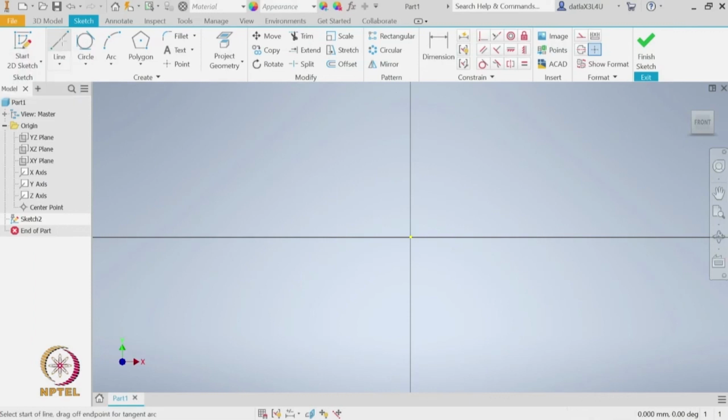So, I can start with a straight line, saying that this is one straight line, 2, 3 and 4 points. I will press the escape button to say I am done with creating these multi segmented lines. Now let us use this extend button. Once I click extend and come to this third line, it suggests that it will extend it until it reaches the first line segment. So, let us select it. This is how we extend a line until it reaches another entity. In this case, it is the first line segment.